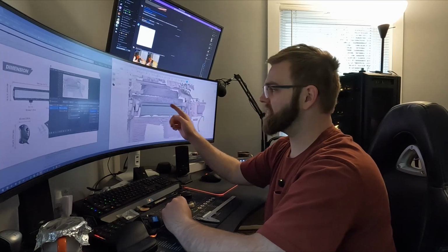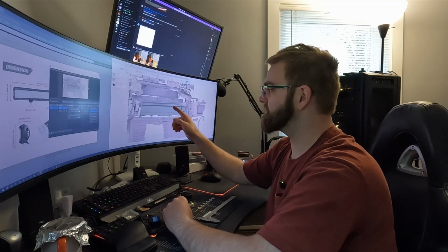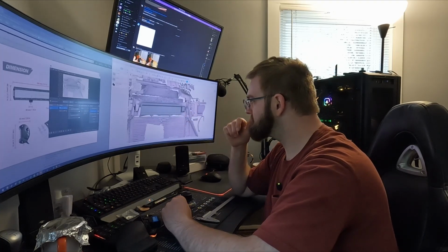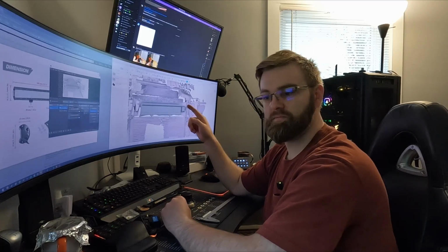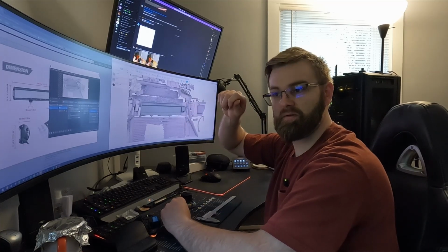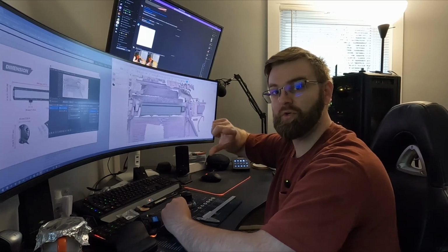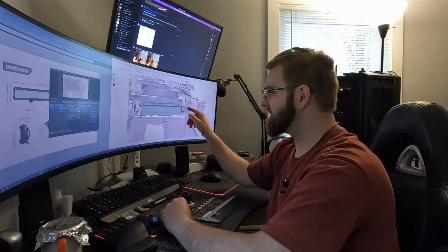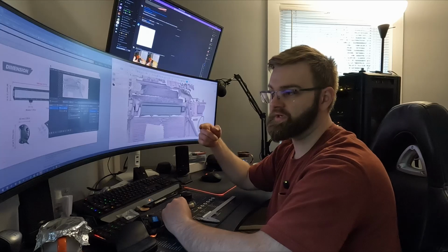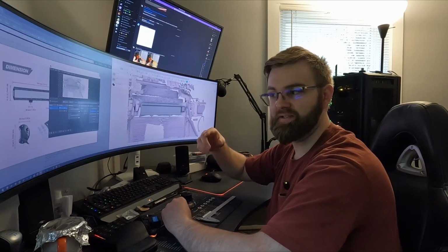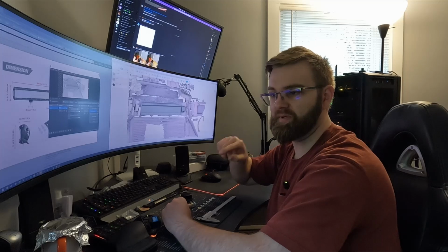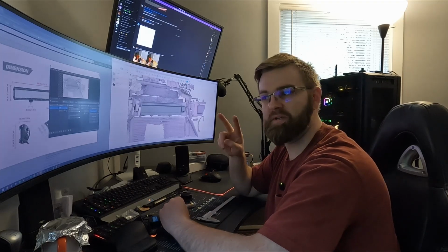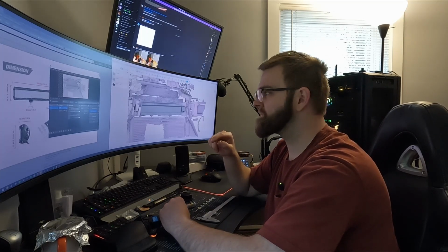For now, I want to put a servo at each end if I do a full length bar. And I don't know if I'll put an arm that mounts to the door and pulls the door around an external pivot, or if I'll put the servo straight through a bearing set where the door pivots, and it will rotate the door at the pivot point. Those are the two kind of ones that are floating around in my mind right now.